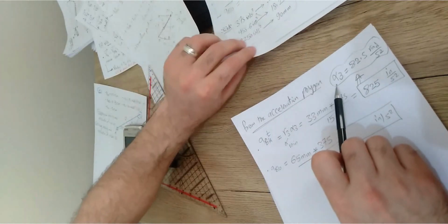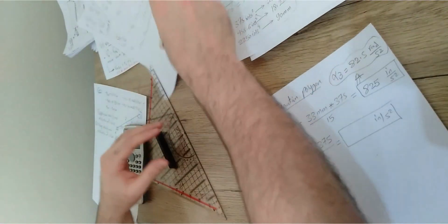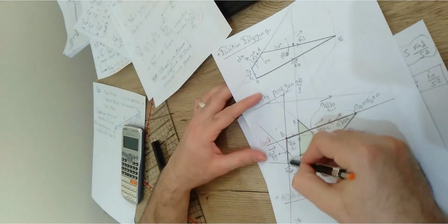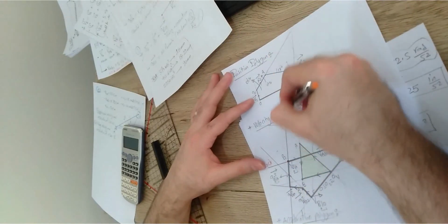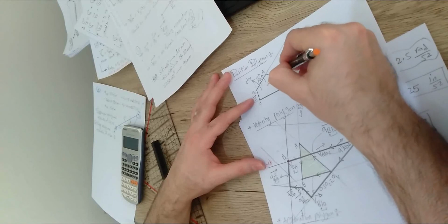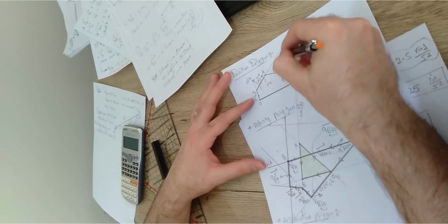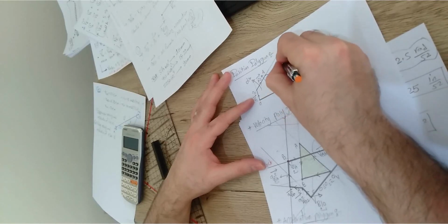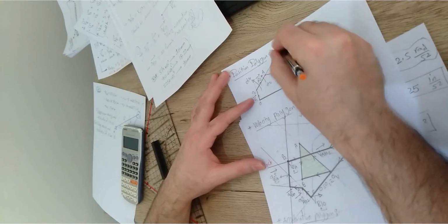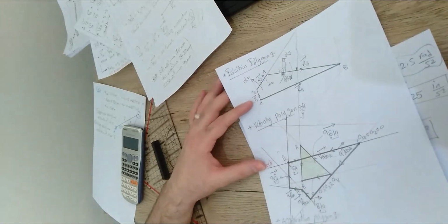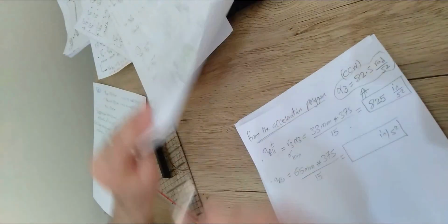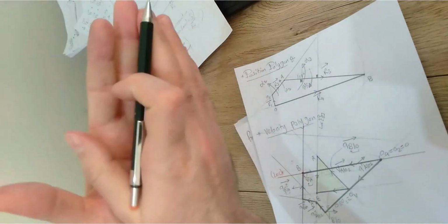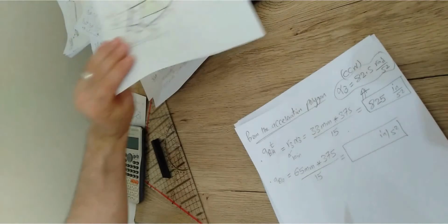How about the direction of alpha 3? Is it clockwise or counterclockwise? We're going to figure it out from the diagram here. The tangential component is going up, right? And it should be perpendicular to the R3. So it should be perpendicular, at 90 degrees to the R3 here, and it pushes up. So what does it mean that it pushes up? It means that the direction of alpha 3 should be going up in the counterclockwise direction. So alpha 3 is going to be in the counterclockwise direction according to the figure. How did we know this? Because it's going up in this direction. Make sense? So this is the alpha 3.